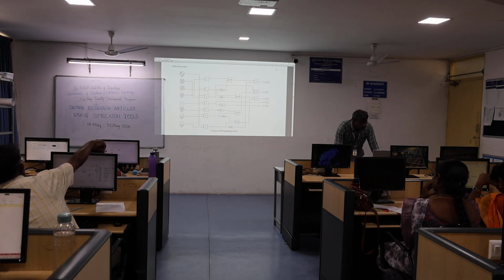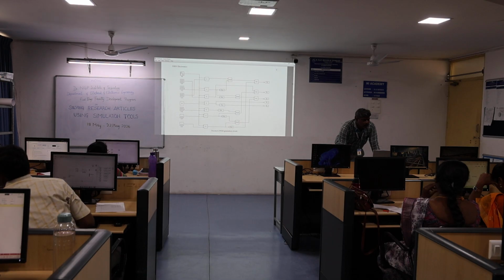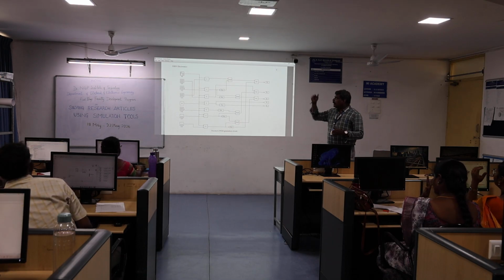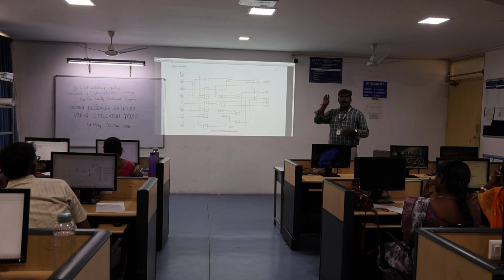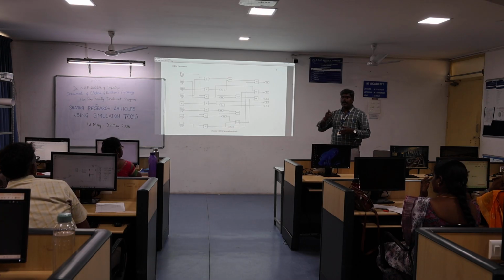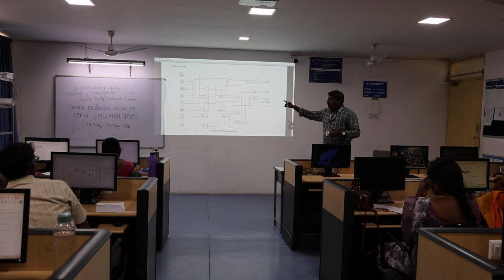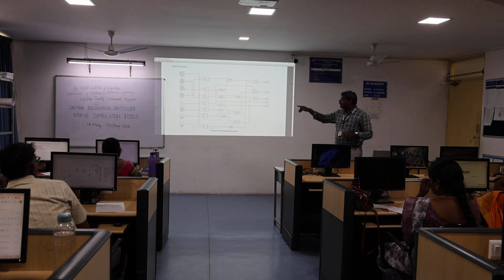So that's why here you have a reference value. You can change only the reference signal. In the sinusoidal sine waveform, you have an amplitude. You can change the amplitude value to 0.8 or 0.6 or 0.4. You can vary the reference signal, and your output voltage is also controlled. But the carrier signal is fixed. You don't change your carrier signal. It is a fixed value. The carrier signal is always a triangular signal.